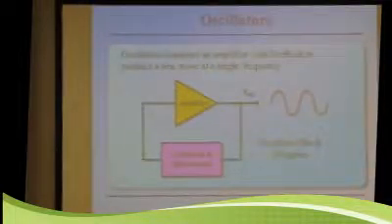And almost everybody here has heard what uninterrupted feedback is like. That's where you have a person with a microphone and you get feedback from the speaker to the microphone. So oscillators do the same thing, but they're doing it in a controlled and carefully designed method. So they produce oscillation at a certain frequency, that is one that is chosen by the person running the radio.